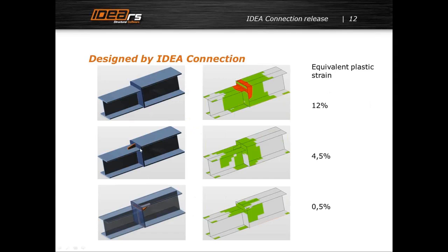And we can analyze such a connection, such a node. We add, for instance, a very small haunch here, but even this small haunch really helped. And in fact, this design is good enough. But you can make it even better with the stiffeners in the direction of the top flange of this beam, and such a design is perfect.